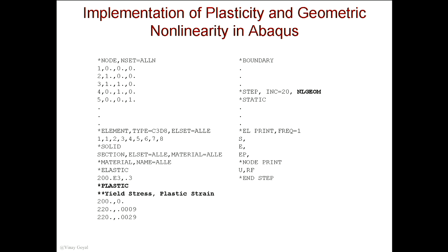Make sure you are putting in the correct data. Say I go to a test lab and get the stress strain curve of the material. The data that may be provided to you is engineering stress, engineering strain. Depending upon the code, whether it's Abaqus or Nastran or ANSYS or all these different codes, they may ask you to put in engineering stress versus engineering strain, or they may ask you to put in true stress versus true strain, and so you may have to convert it. Okay, just keep that in mind.